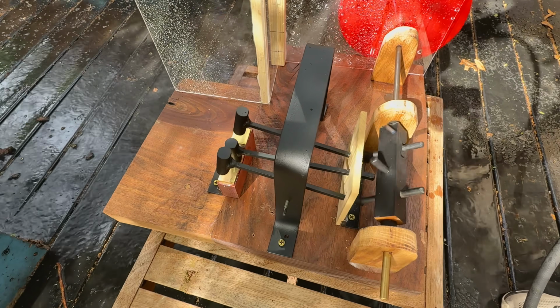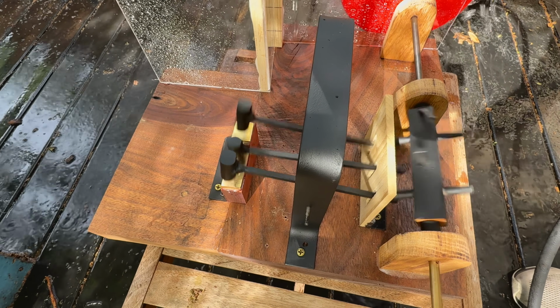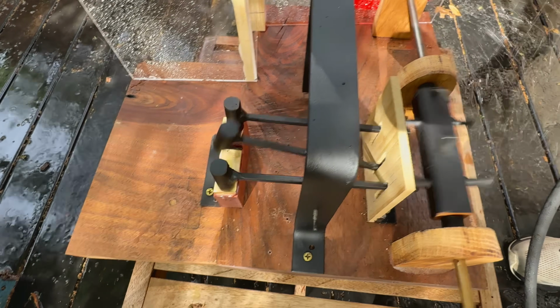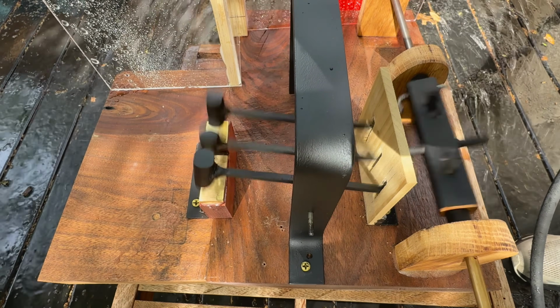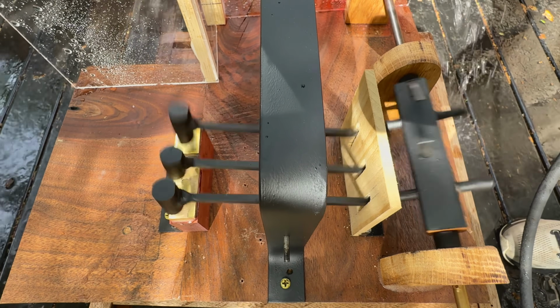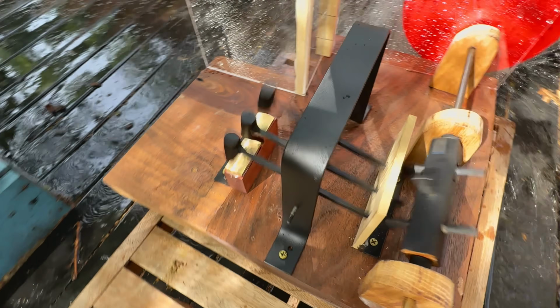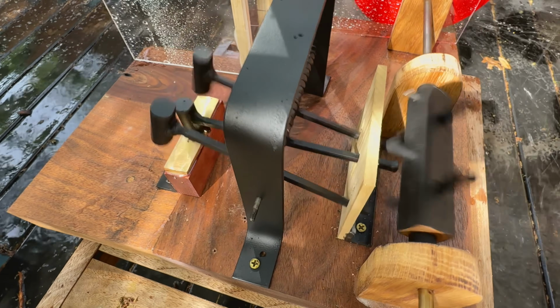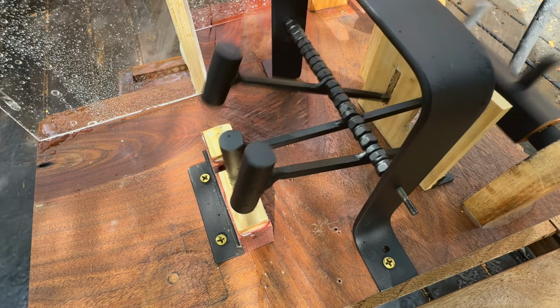However, triphammer-style tappets that push up or down on something set into their path have a serious limitation. The gap between the tappets means the resulting motion will be intermittent. The tappets for a single machine attachment should be evenly spaced. If not, the tool they act upon does not have time to repeat its full cycle. Anticipating a nice rhythm of the tool is desirable, but what if you don't want intermittent motion that is only up or down or left or right?